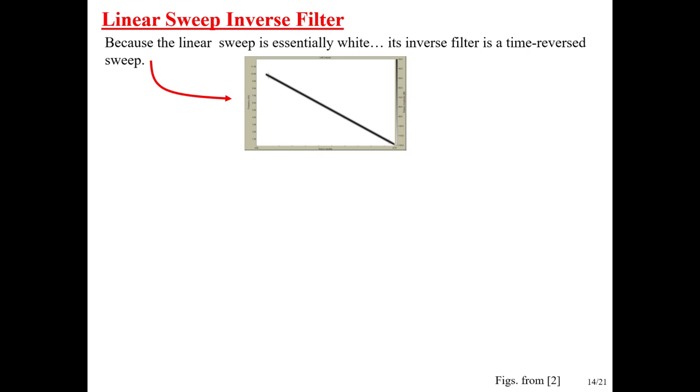It's not necessarily easy to see that a linearly swept sinusoid really does have a white nature. So its spectrum is flat. It is true. And you can prove it analytically, but you can also kind of think through it, right? The sinusoid is spending equal time, so to speak, at every frequency. Its rate of change as it's sweeping through the frequencies is the same. So it's kind of like it's at all of those frequencies for equal amounts of time, so to speak.